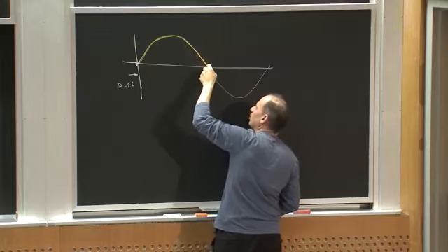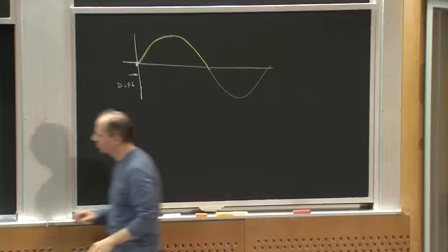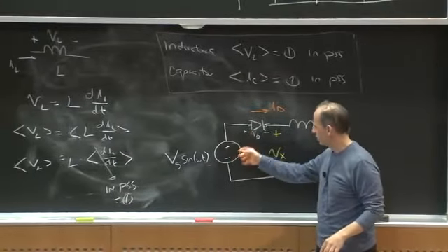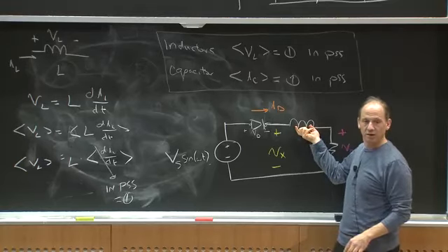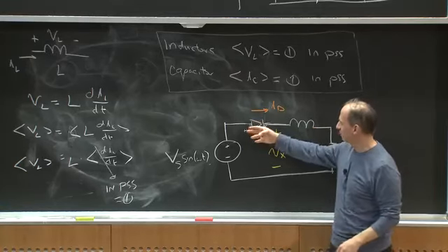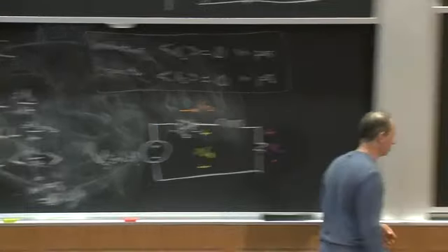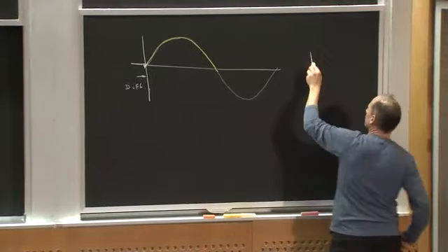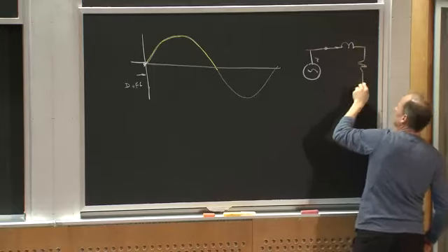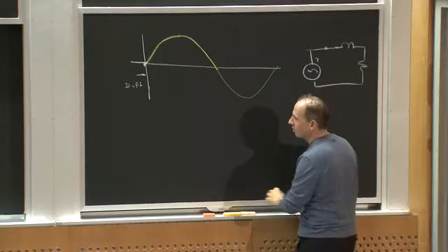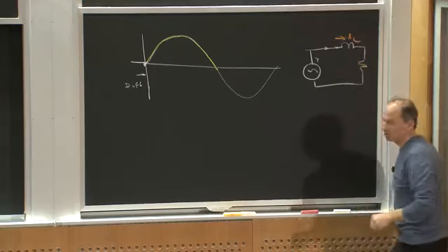What's going to happen here, though, right? Is the diode going to turn off here? Well, let's think about what this current would be. I could analyze, and I could say, look, at t equals 0 plus, the inductor current is 0, and at that point I've replaced this switch with a short circuit. I can analyze that circuit, right? That circuit's just this. I can analyze this circuit for the inductor current, knowing that IL of 0 is 0.